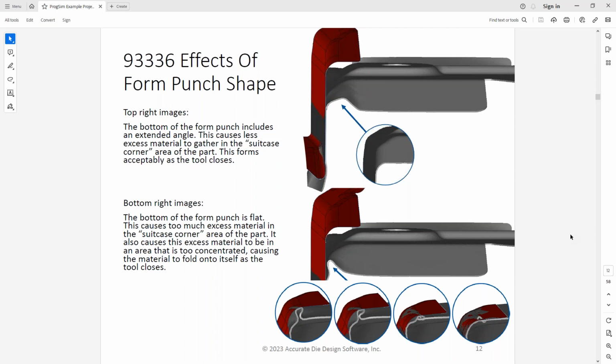Yeah, in fact, on this one, Matt, in the top picture, above that arrow a little bit, that pressure pad along that entire angular surface is a little bit shorter. The flat portion of it is shorter. Now if you go down to the next picture, that flat portion is longer, and that's why it caused it to bubble up so much more right there. Because if you look, the pads are in about the same spot. So there's so much that can influence it, and you're influencing it in minutes rather than in days, because otherwise you've got to cut metal and then try it, et cetera.